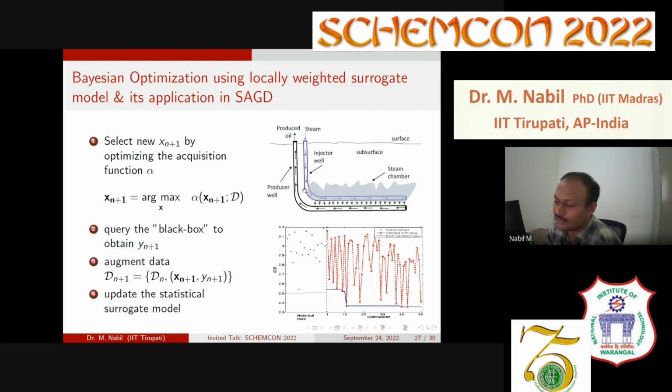That is what we call the steam to oil ratio. If the steam to oil ratio is as low as possible, then you can say it is a measure to quantify economic performance. If it is low, it means the amount of steam required to get the required amount of oil is less, which means I need only a limited amount of energy sources to produce steam.